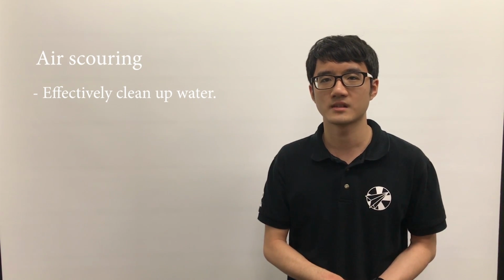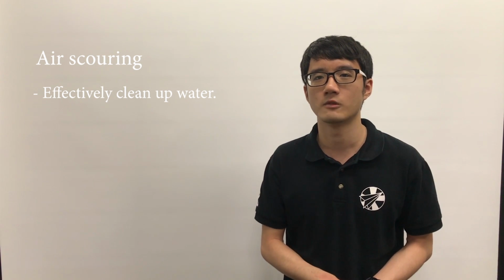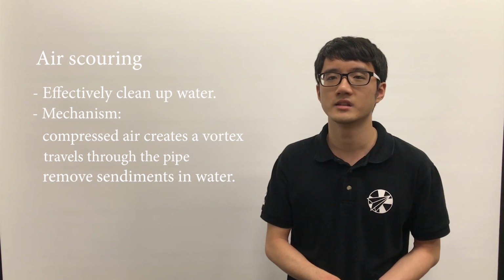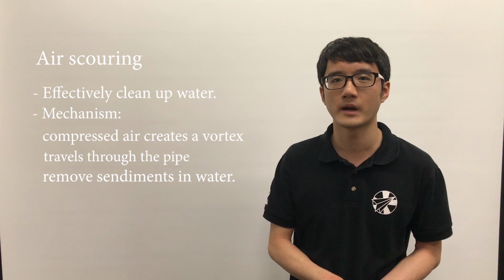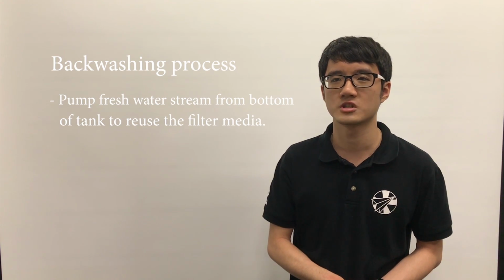Air scouring process is an essential process in water treatment because it effectively cleans the water. The mechanism for this process comes from the compressed air that creates a vortex that travels through the pipe which removes sediments in water. To maximize the scour rate, it is combined with the backwashing process.